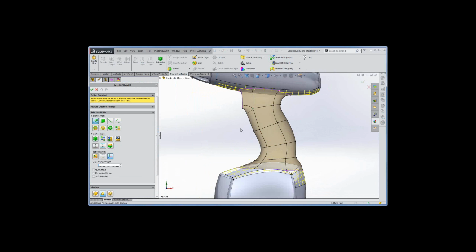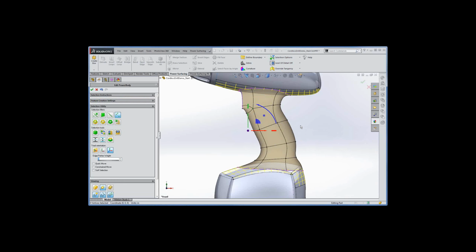So I'm going to go to level 2, and then I'll select a few vertices here and pull them out and make some grips. So that gives us more power to add detail. But here's the really cool thing: I can go back down to my level 0, level of detail off, and it's going to update in a sec. And what it's going to show me is the changes I made on the higher level of detail, but now I'm back to the point where I can still choose my original geometry and move it around, making those big, smooth changes much easier to do. And it does its best to keep the relationship between the other levels' additions in there.